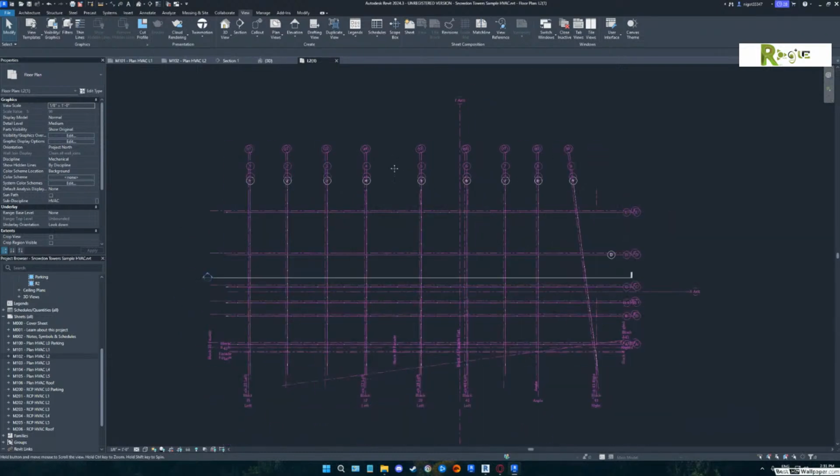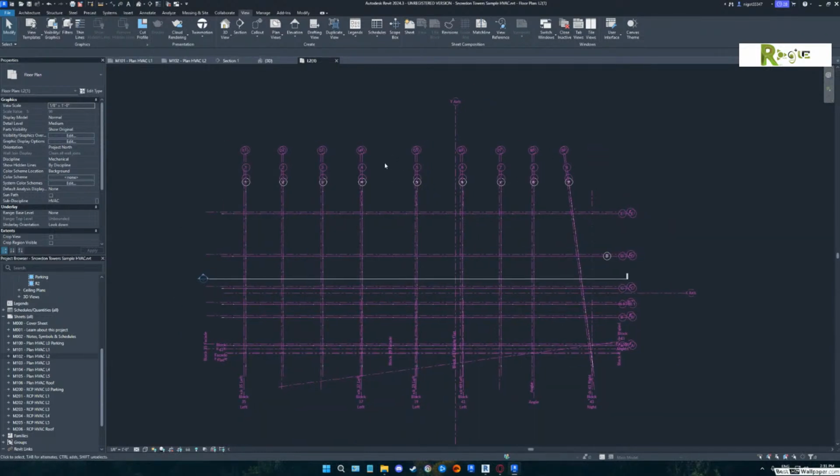Okay. And you would just create this view, right? I would create that view because otherwise what's going to happen one day is you're going to be going in there and you're going to be moving pipe and moving duct trying to get things to fit. And you're not going to realize, like they didn't, that the plumbing file was moved. And you're going to be moving all this ductwork out of pipe that's not actually even there. Yeah. Then when it gets into the right spot, you're going to be like, oh, damn, I got to redo all that.